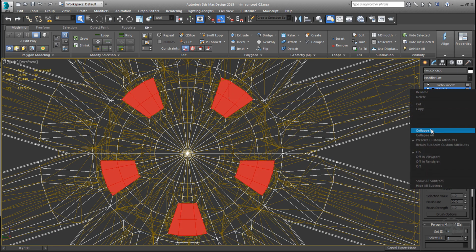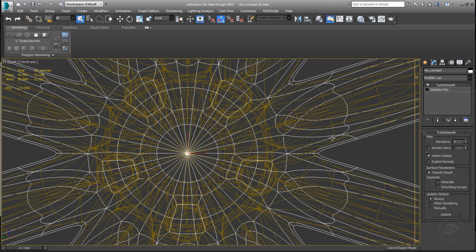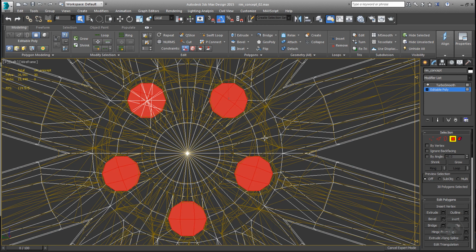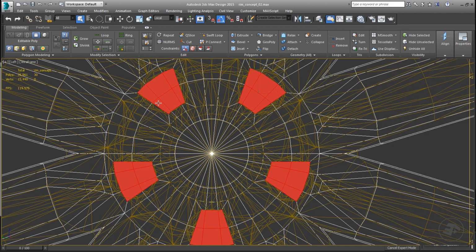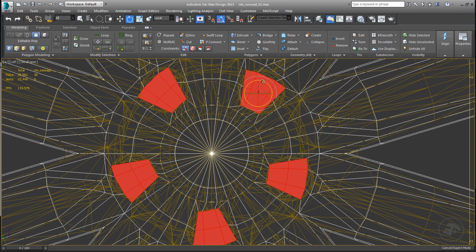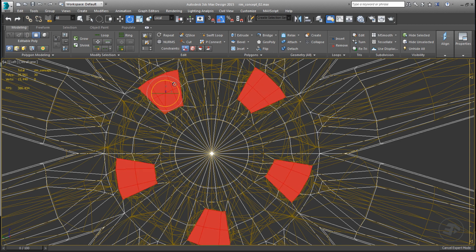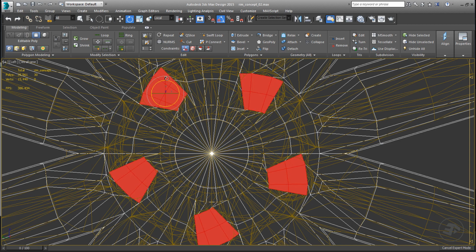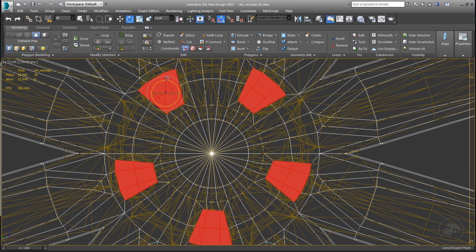When reaching this point, I have to use editable poly geometry. Use the Rotation tool with local as reference for the coordinate system, and the tool in the middle of the selection to change the rotation of the selection to help the script processing. However, this technique is not always guaranteed.